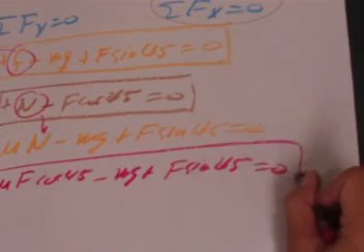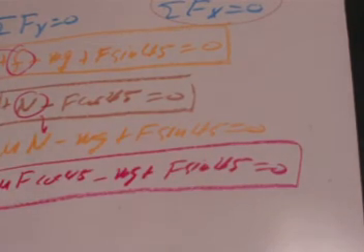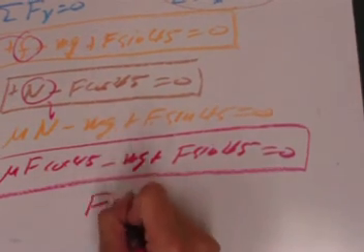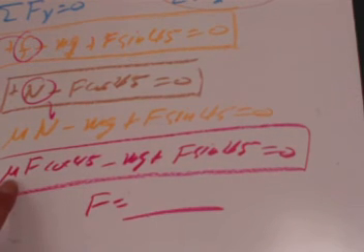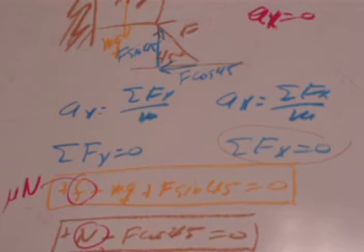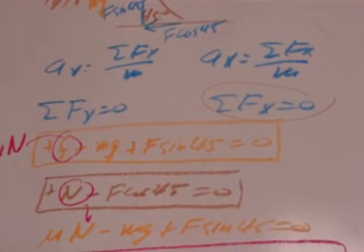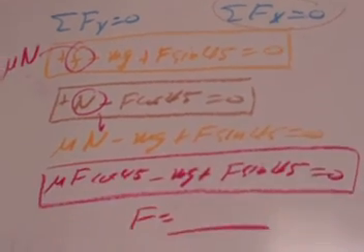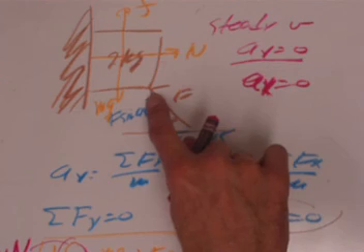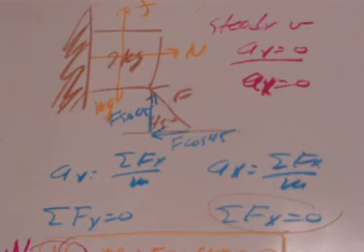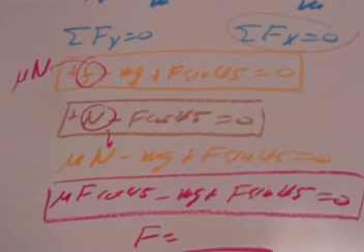So I'm going to end the video here because I think the solution is at hand. There's one big equation which you can solve for F. The only unknown in this equation is F now. I believe it was a wood-on-wood type of problem, so you can find the coefficient of friction for that in your problem, or if there's two different materials that are quoted in your problem, you can use those. Cosine 45 is known. The mass of the block was known to be some number, and g is 9.8. So you know everything. You can just solve for F. And that would be the force at which this unknown force is going to have to push on the block in order for it to lower at the steady speed indicated. Nice problem.